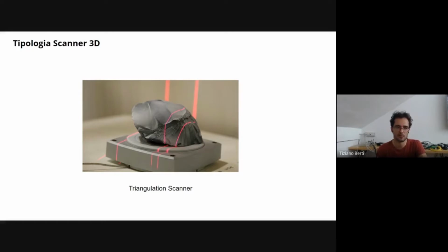The triangulation scanner remains a slow technology compared to other ones. And the object is usually put on a turntable and will turn during the scan. So this is pretty difficult to do with a human. Imagine being on a stool that turns really slowly and being asked to stand very still.